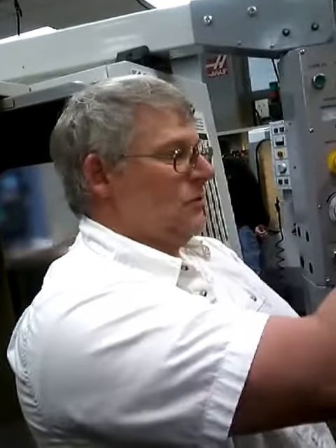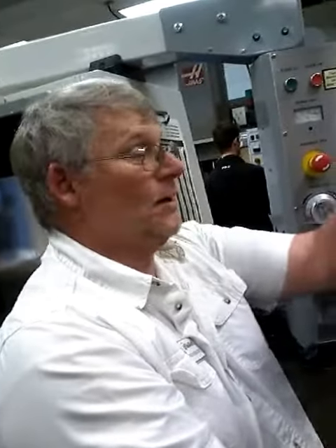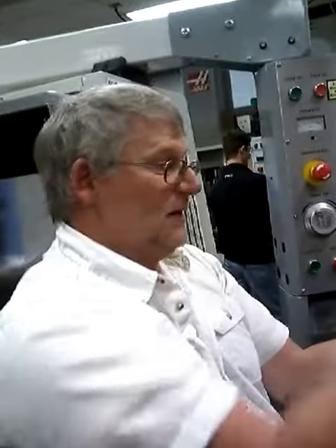You can have G54 for this zero, G55 for that zero. Once it finishes the G54 part, it goes to G55. In your program, you have to tell it, G55, go run this part. I could run the same program, one on the left side and one on the right side, and I can tell it, G54, run the program. It's going to run it over here. I tell it, G55, run the program again. It's going to run it over here. Because I set a G54 up over here as zero, and a G55 up over here as zero.